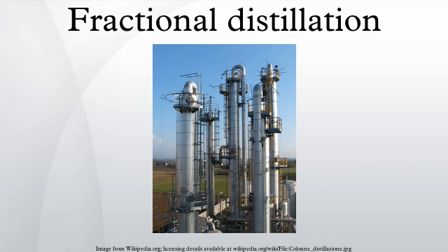In industrial uses, sometimes a packing material is used in the column instead of trays, especially when low pressure drops across the column are required, as when operating under vacuum. This packing material can either be random dumped packing such as Raschig rings or structured sheet metal. Typical manufacturers are Koch, Sulzer and other companies.